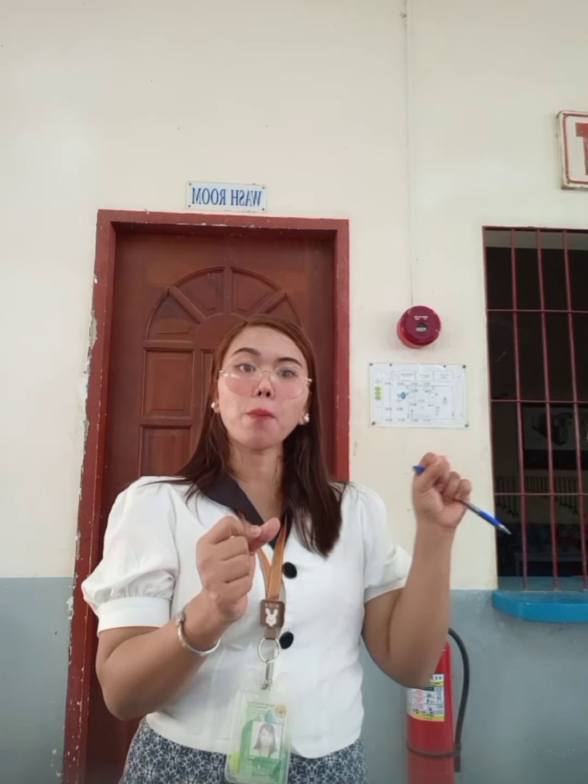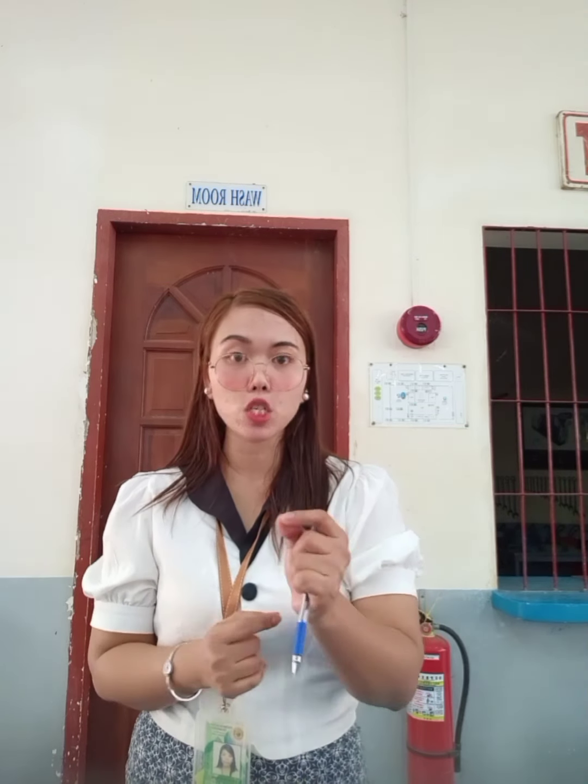Okay? So second, switch off the tools before connecting them to a power supply. Kasi pag yung power tools na yan is naka-on before mo siya i-connect sa power supply, there's a tendency that it will cause you an injury. Delikado, halimbawa, angular grinder, and you are not aware that yung power tool pala is naka-switch on.